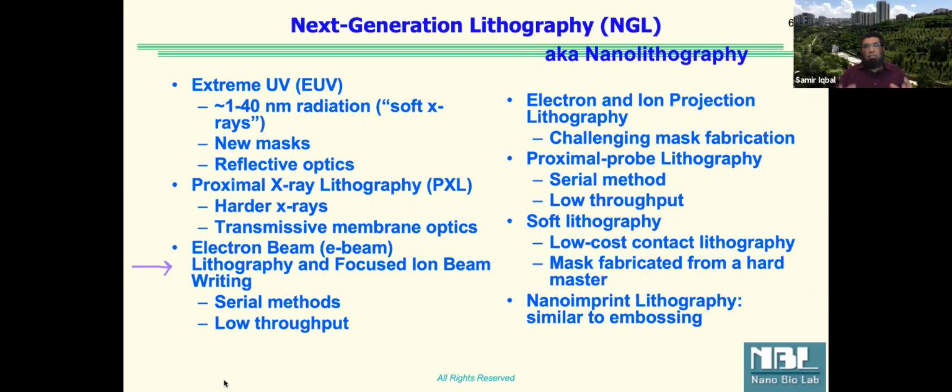diffractions. So we have to have specialized equipment where we create vacuum, we pump everything out, and then we have a bunch of lenses. But in this case, the lenses would be electromagnetic coils to bring the beam very narrow, and then use it to write the feature or whatever device VLSI design we want to write. So that's what we do with electron beam. Let's get started and we'll look at all the others as we build upon it.